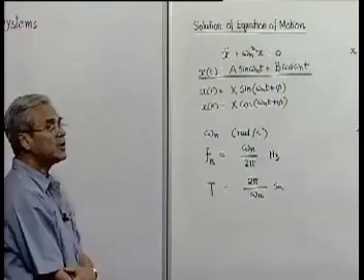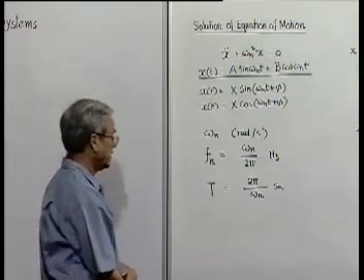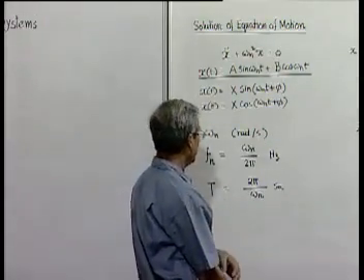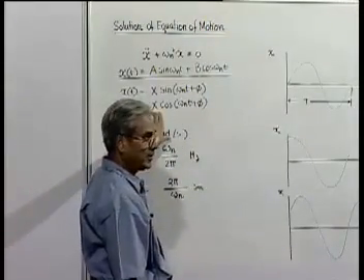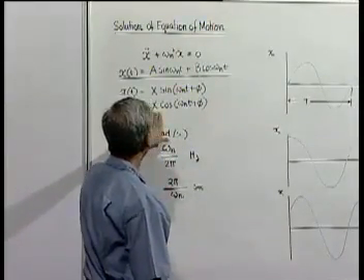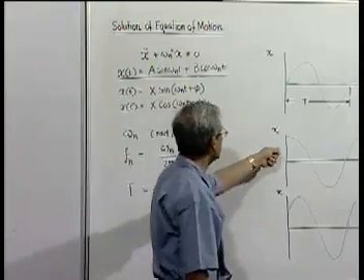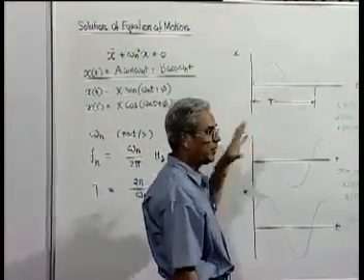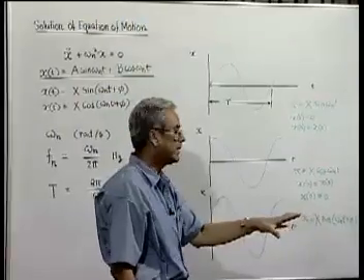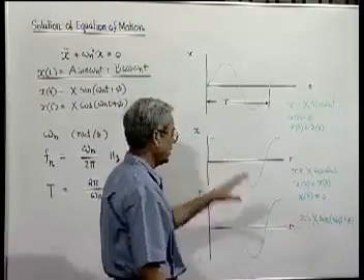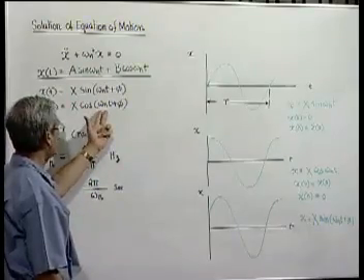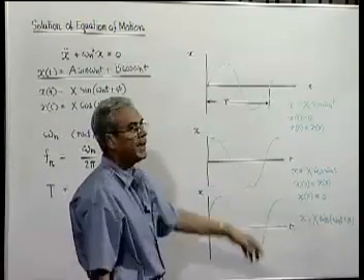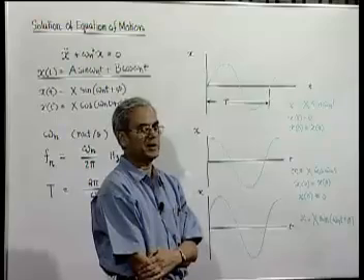The importance of this study is one thing to be kept in mind: you have noticed that the determination of x is not a system property. It will depend on how much displacement you initially gave, how much energy you have put into the system to initiate vibration. On the other hand, the frequency with which it is oscillating is a property of the system.